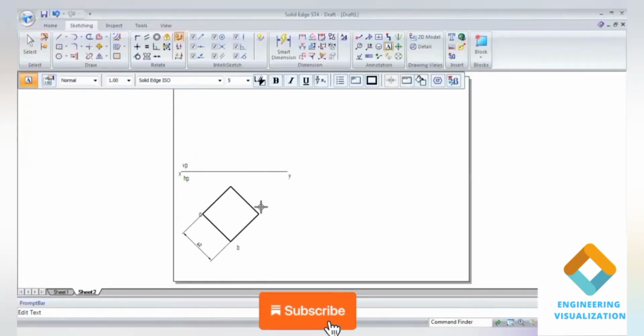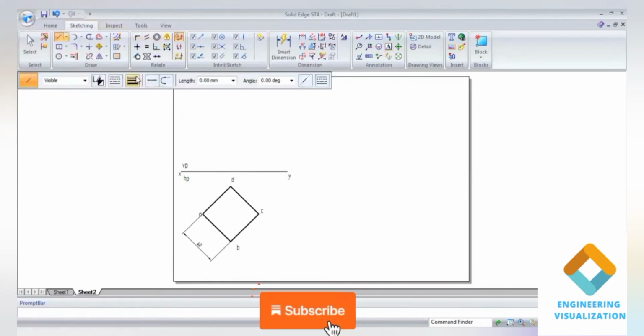So here top view notations can be written ABCD. Since it is a pyramid, we need to draw the slant edges as thick lines. If it is a prism, it should be thin lines. So you all should know this difference. So thick lines we have drawn.